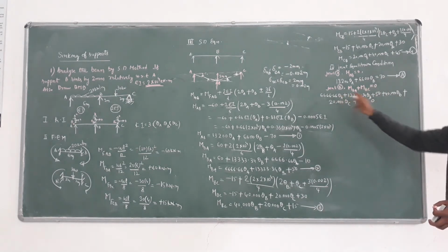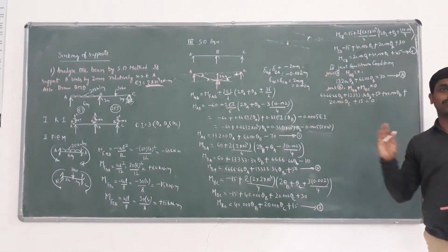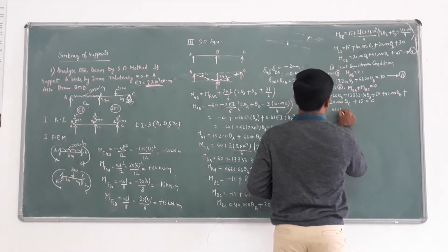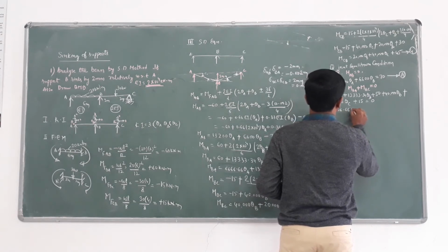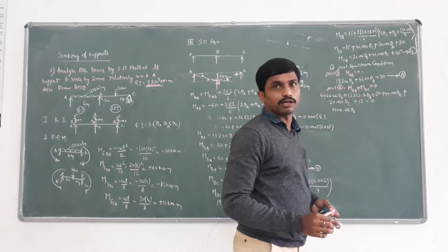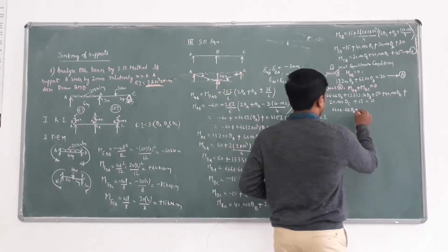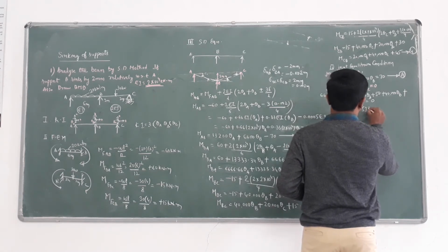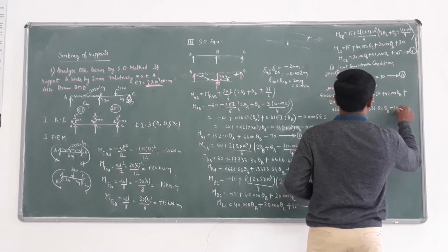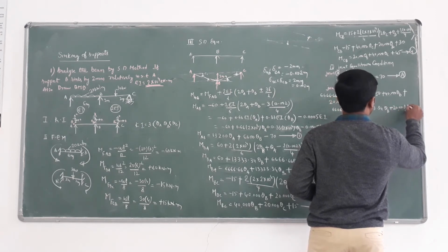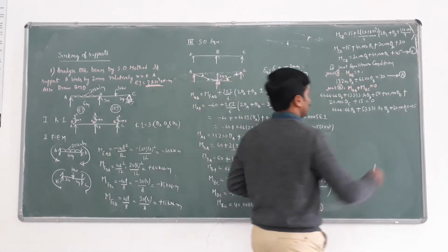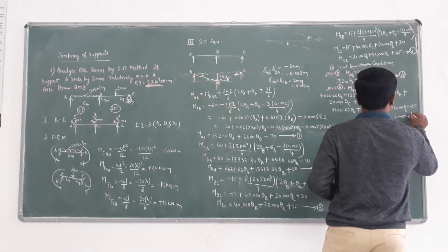First theta A, next theta B, theta C. There are three unknowns. So first theta A, only one theta A value: 6,666.66 theta A plus theta B, 40,000 plus 13,333.34, it will become 53,333.34 theta B plus 20,000 theta C equals minus 15. We take this as equation B.